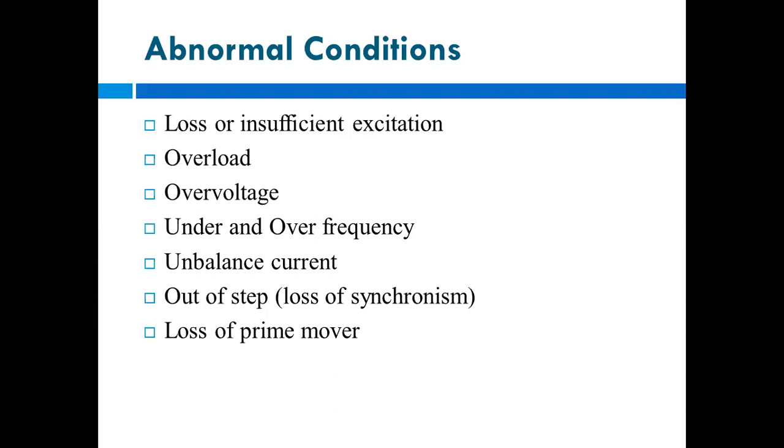Okay, then next is the under and over frequency. It means whatever the supply frequency given, in India it is 50 hertz. So if that frequency becomes low, or if it becomes more, then also there will be a fault in the generator.